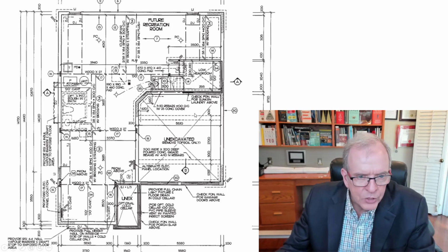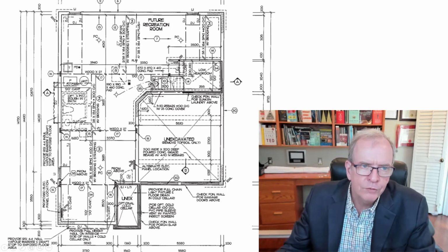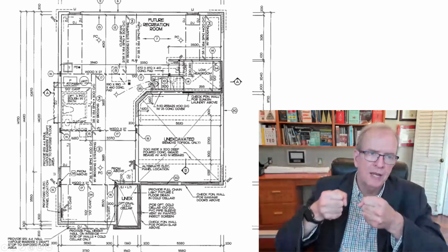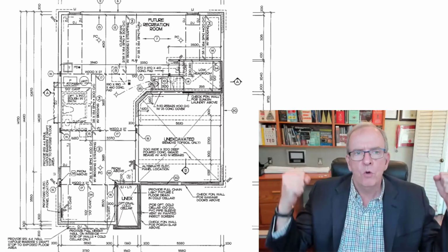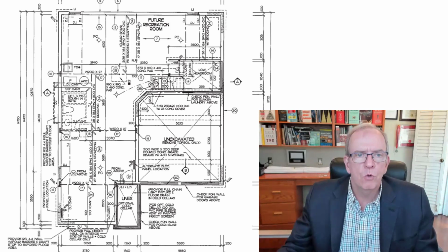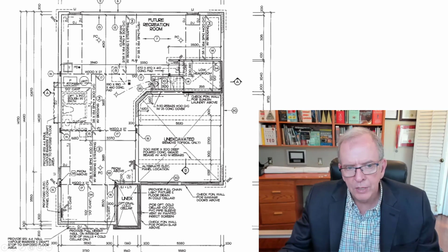There's also some information here where you would have to put 320 rebars, because this area here is considered laterally unsupported. That means there's only a stairs there. The rest of the first floor is supported by the sill plate and the joist. Sill plate's anchored there with anchor bolts. The joists go on top, the plywood. It's holding the whole foundation wall really solid, but this section is unsupported because it's just got a stairs beside it. And you've got the weight of the backfill over here and the concrete slab, and so they put in some rebar here, 320.